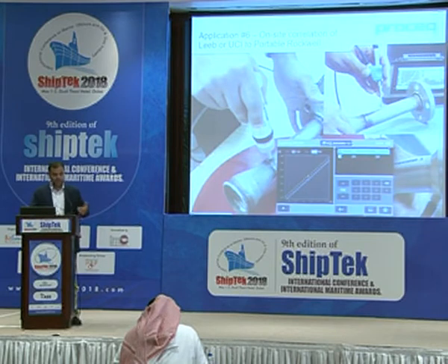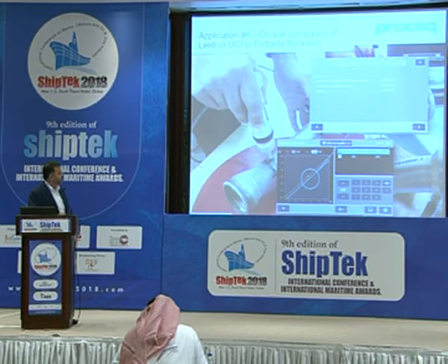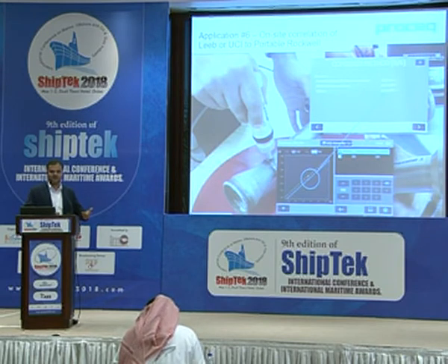And also correlation, on the device itself, we can also correlate one hardness technique to the other, basically by just shifting the curve by just 1 point. It's a 1 point shift or 2 point shift, or we can also do the polynomial shift. In this case, we have just shifted by 24 Vickers, basically. Portable Rockwell, it was 25.6 microns indentation depth. UCI gave 231.3 Vickers, so there was a difference of minus 24 Vickers. So we shifted the curve by 24 Vickers, and then customizing your own curve or calibrating using the hardness technique, we can calibrate and then measure the hardness using the customized curve.